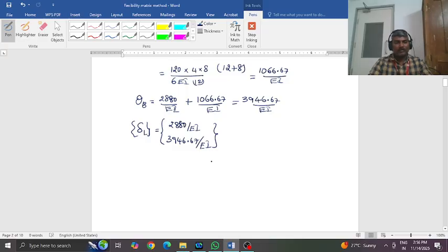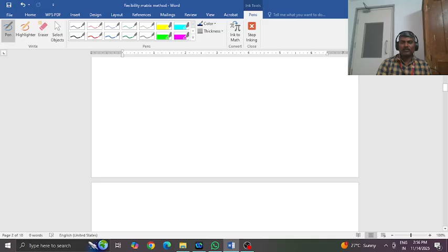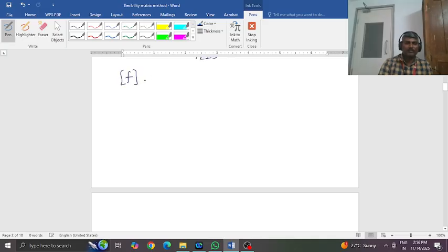Okay, right. Next, once you have formulated the delta matrix and delta L matrix, it is our job to develop the flexibility matrix and its inverse, to substitute into the compatibility equations. So let us try to evaluate this matrix. As the static indeterminacy value is 2, the flexibility matrix will become 2 by 2. If you have SI value 3, it will be 3 by 3. Here we will be finding these values. Because of symmetry, F12 is equal to F21. So how do you find these values?